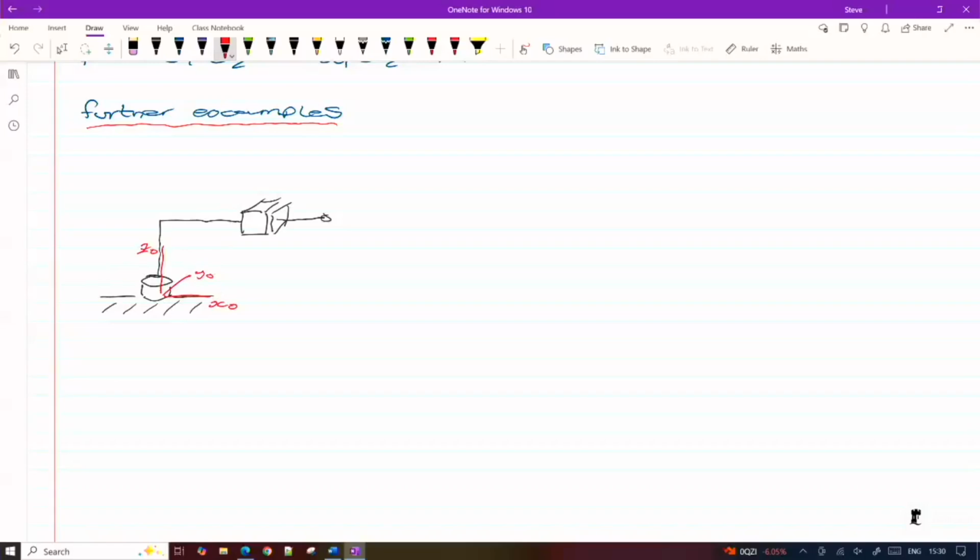For the inverse kinematic approach, I'm not really bothered about the rest of the sets of coordinate axes along our robot manipulator. You do need to introduce all of those when you do a forward analysis, but for this inverse analysis, you don't need to draw in all the frames, but you do really need to draw in our fixed base frame, at least. And just a reminder, should I do that now?